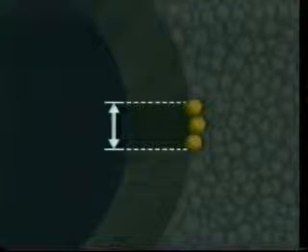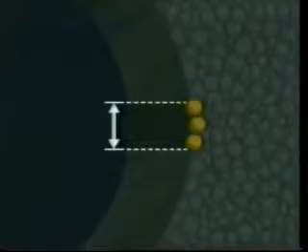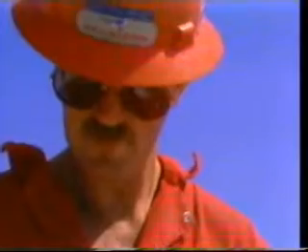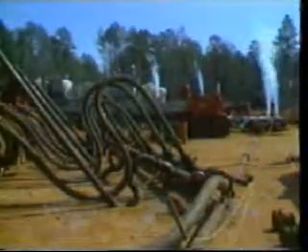Field experience and filter theory have shown that sand particles greater than 1/3 of the slot size will effectively bridge off a slot because of grain interference. This same theory has been applied to hydraulic fracturing in determining the required induced fracture width that would accommodate a given size proppant during pumping. Slotted liners are more suited to medium to coarse-grained, moderately uniform sand that will quickly build up a highly permeable rubble zone around the screen.